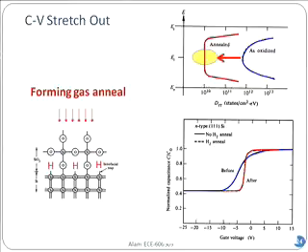And then as you go through the threshold, flat band region and gradually go from accumulation to the inversion region, you can see on the other side, starting from minus 10 volt, it is essentially flat at a lower value of capacitance. What frequency is this? This is at relatively high frequency, right? Because otherwise it would have gone back.